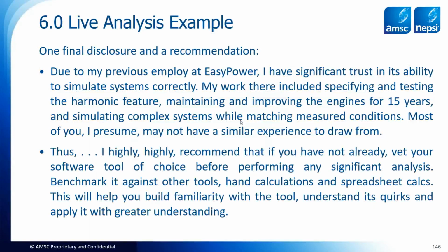And I wanted to see for myself how they would compare. And I basically got one-to-one, both of them laying right on top of each other. Just slight differences because of the resistance skin effect and proximity effect was modeled slightly differently there. But as far as the resonant points where they occurred and the general amounts of amplification, it came out to be almost exactly the same.